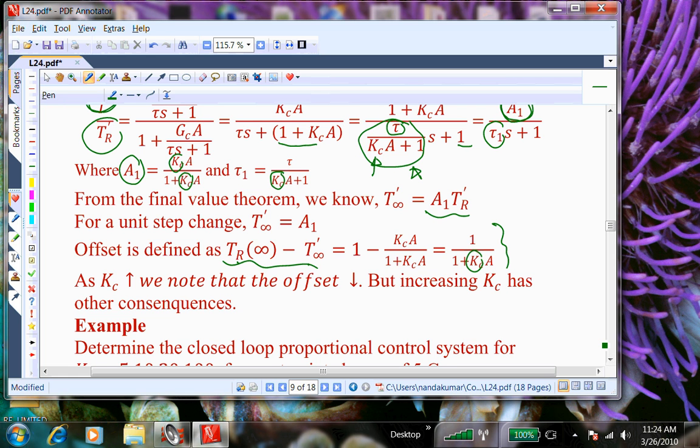Now, I need to relate this to stability. How do I relate the effective transfer function that I have to the stability? So if I have something like G1, G2 divided by 1 minus, say, G1, G2, or 1 plus, whatever, how do you determine the stability of such a system? We are now talking about stability not of the dynamical system, but the stability of the feedback control system, because this is the effective transfer function for the feedback loop.